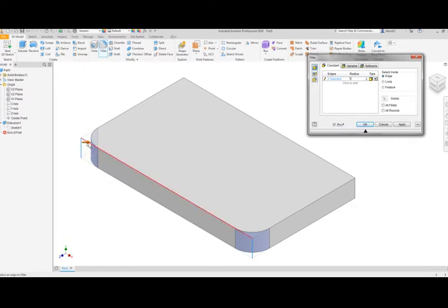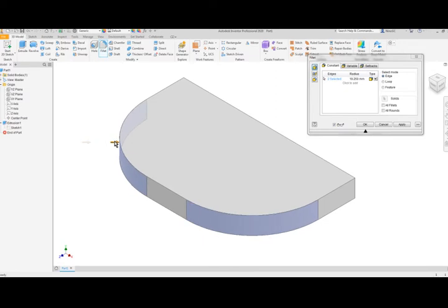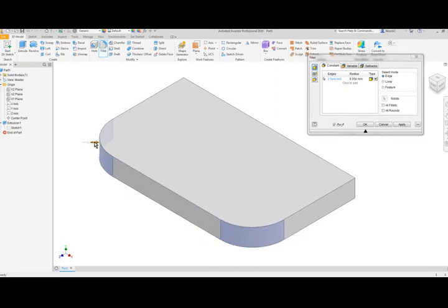However, we can also click on the little yellow arrow, and holding down the left mouse button, we can do a what-if scenario, such as testing out to see how large or how small we would like the fillets. As we do that, the radius callout automatically adjusts to indicate what the size of the fillet is at that point. Here we've specified 2 edges.